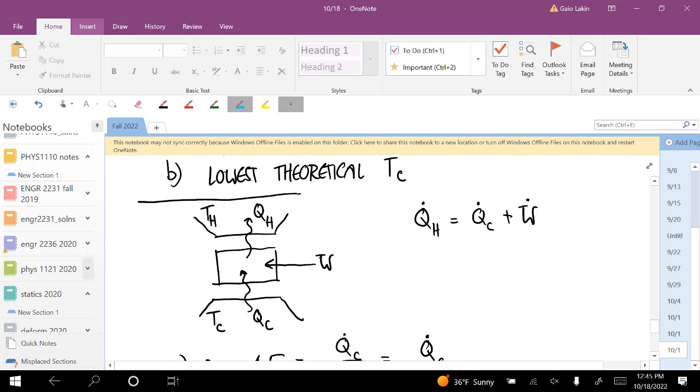But you can make it a lot more efficient if instead of air, because I'm imagining this happening with air, you devise a refrigerant that is right near its saturation temperature and pressure, so when you remove energy from it, it changes from a saturated gas to a saturated liquid. And then when you add energy to it, it goes from a saturated liquid to a saturated gas. Now you haven't changed the temperatures at all because you're at that phase change temperature. But you've allowed for a lot more transfer of energy to happen with each one of those cycles.